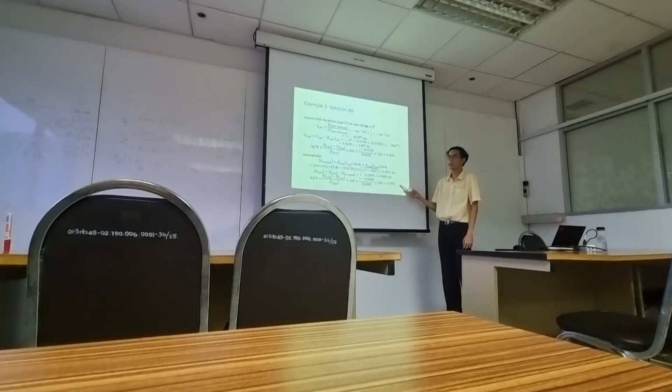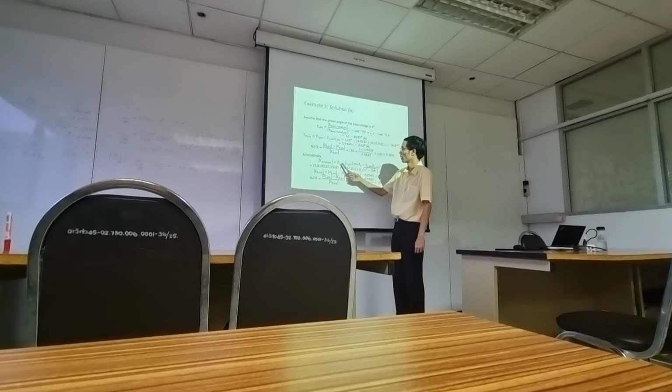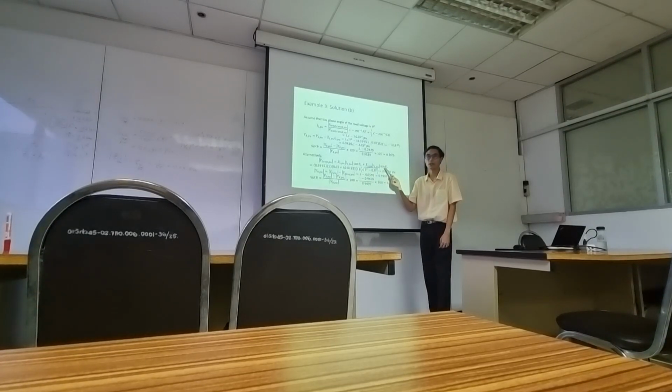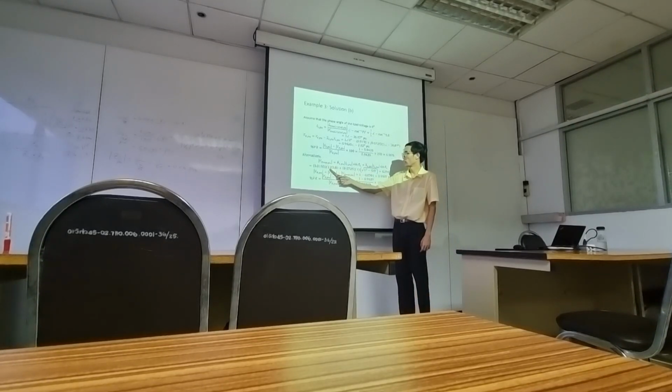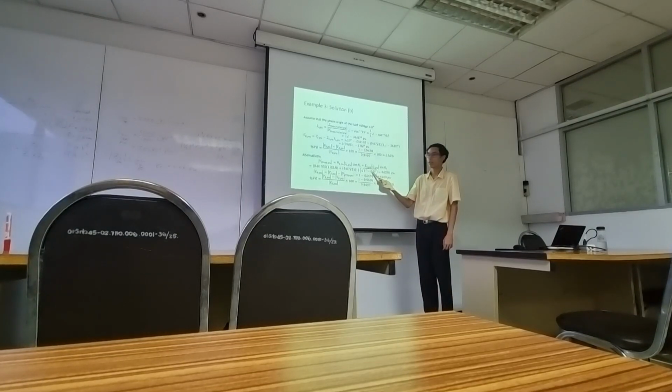Then you have an alternative way, just the approximation method. The voltage drop equals R I cos theta L plus X I sin theta L. We have already talked about this. Use the same equation. This is R I cos theta, this is X I, and then this is sin theta. So you get this in per unit. The voltage drop would be 0.0591.